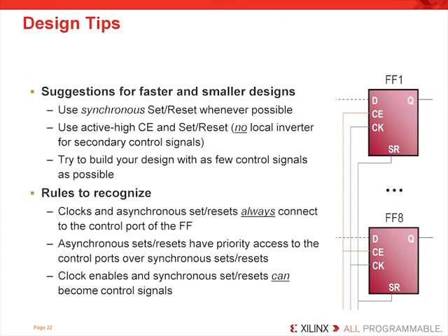Clocks and asynchronous sets and resets always connect to the control port of the flip-flop. This is probably the 10th time we've mentioned it, and probably at this point you're going, okay, I get it. Asynchronous sets and resets have priority access to the control ports over synchronous sets and resets. And lastly, clock enables and synchronous sets and resets can become control signals, and that flexibility is why we strongly recommend their use.